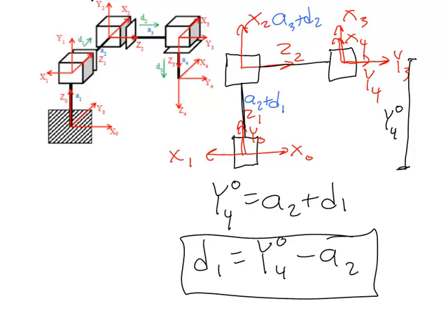I did the Cartesian manipulator derivation for you first because the Cartesian manipulator derivation is the easiest one. In general, the more prismatic joints that you have in your manipulator, the easier it is to derive the inverse kinematics. And the more revolute joints you have, the more difficult it is to derive the equations. In the next video, I'm going to show you an example with a manipulator that has some revolute joints as well.